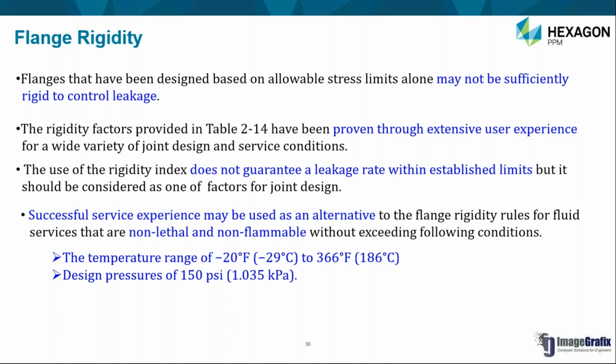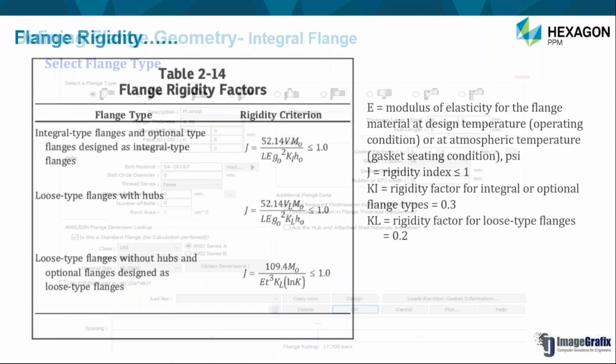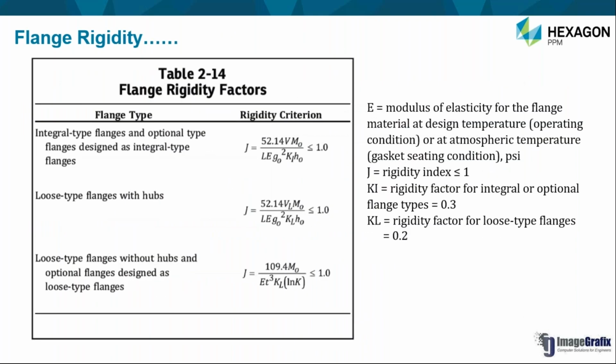So can we say now that the flange design is completed? Yes, we can say that, unless there are some external loads which are going to come on your flanges. Then we can conclude that for the stresses and rigidity index which we have checked, the flange design is completed.